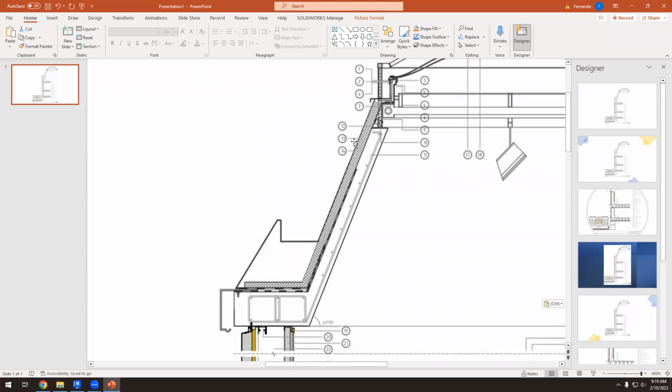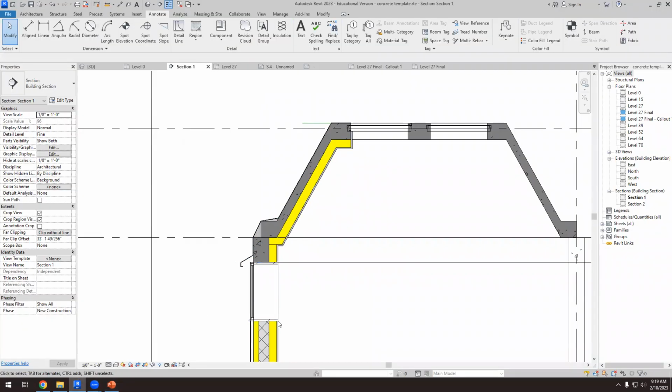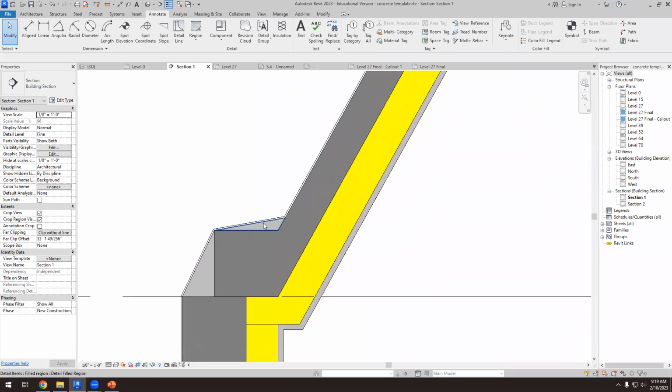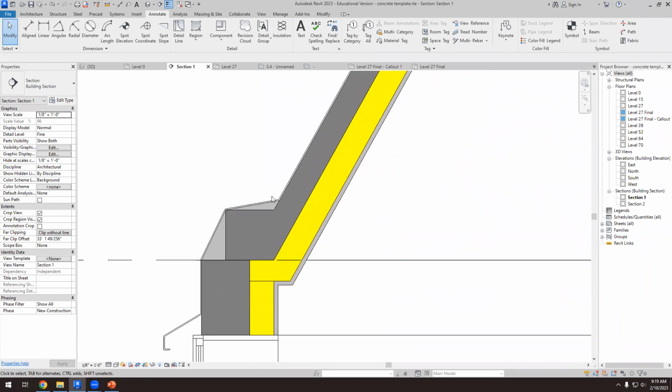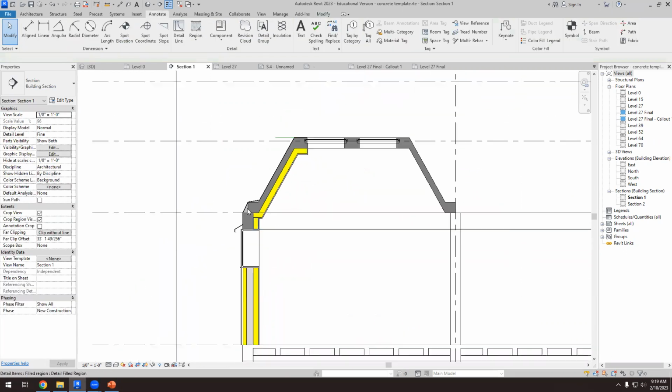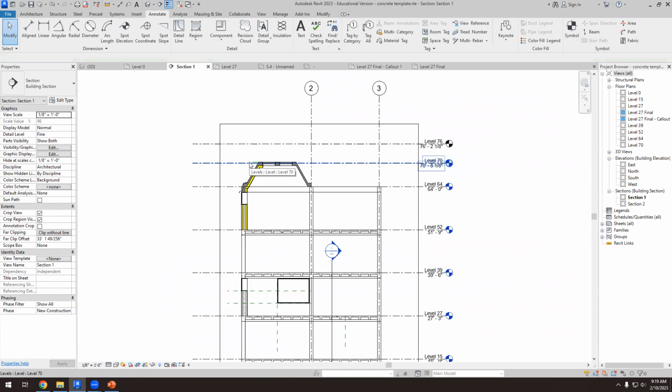Next time we'll try to do this one, because now I think applying the thermal insulation outdoors would be a better option. But anyway, the idea is that we don't have to interrupt the thermal insulation. It can be indoors or outdoors. But we don't interrupt thermal insulation, and then we don't expose concrete to the rain. So we have this metallic thing here.